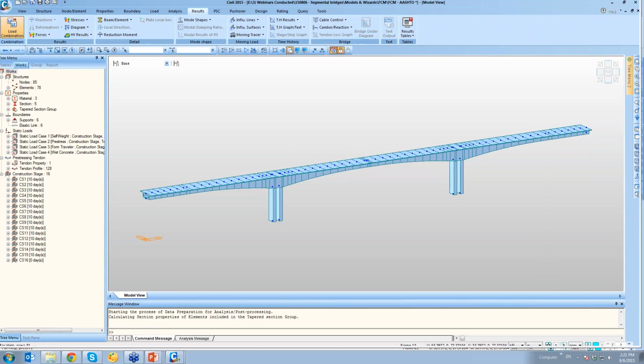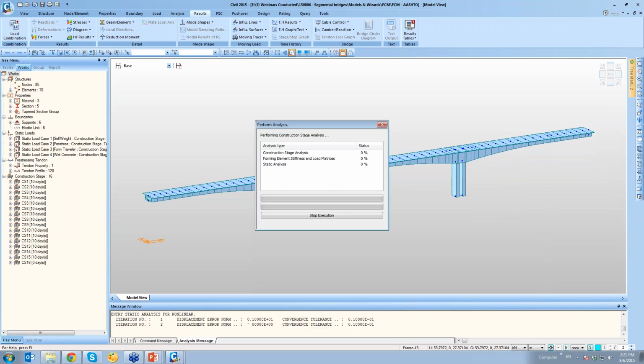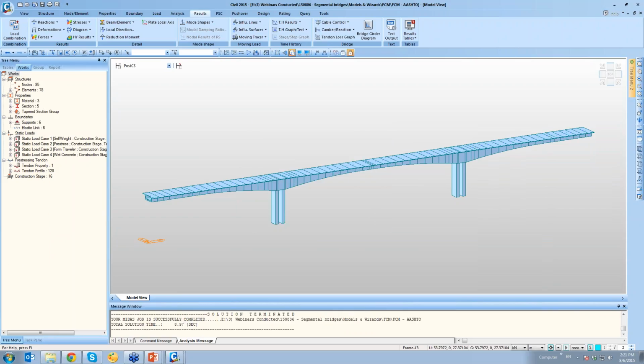What do you mean by wet concrete load? Basically, sir, if the method for balanced cantilever bridge construction is cast-in-situ, your form traveler would be there, and in that your wet concrete would be placed. Based on the cross section as well as the length of the segment, the weight of the wet concrete or the green concrete would automatically be calculated, and that vertical load as well as the moment would be applied to the existing section. I'll just put it for PSC design as well.